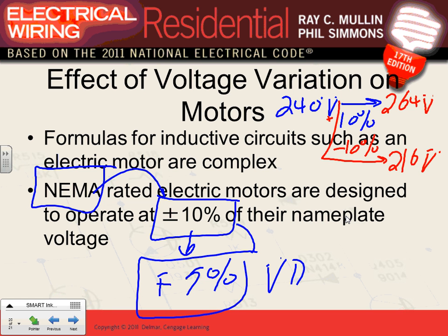So this is what we design based on, 5% less voltage for our equipment, and the manufacturer allows 10%, so that we still have an area of caution and safety. Does that make sense? Does it make sense? Here's where the equipment functions, here's what we designed, we're almost half of it, getting even more stringent in our design. Does that make sense, guys?